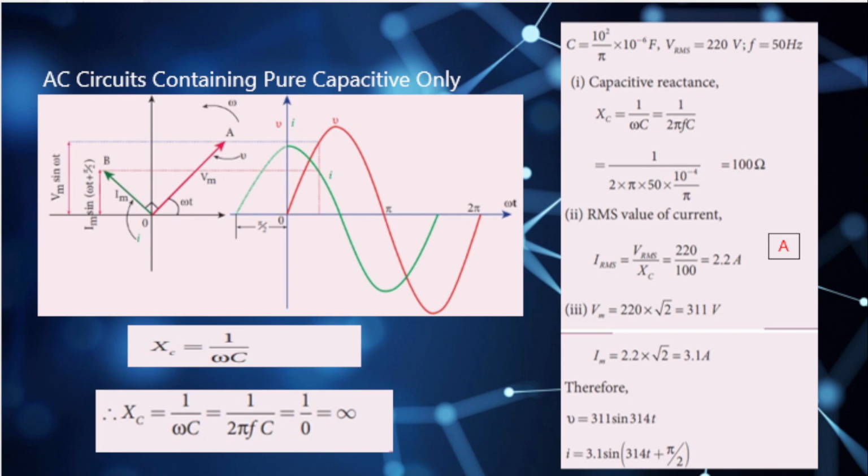In case of an AC circuit containing pure capacitance only, the current leads. Look at this. We see the inverse. The current leads the applied voltage by an angle of pi divided by 2, or 90 degrees. And the power factor of the circuit is leading. Perhaps simply to remember a capacitive circuit as current leads voltage by 90 degrees. So we just swap what we previously stated concerning our purely inductive circuit.